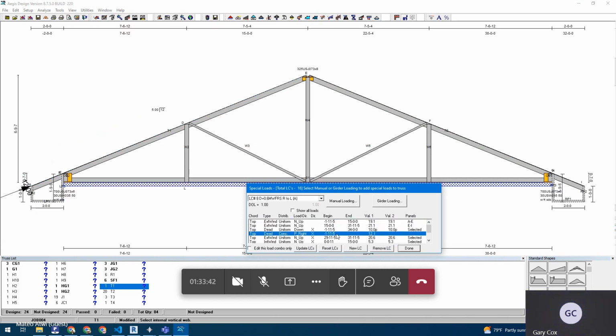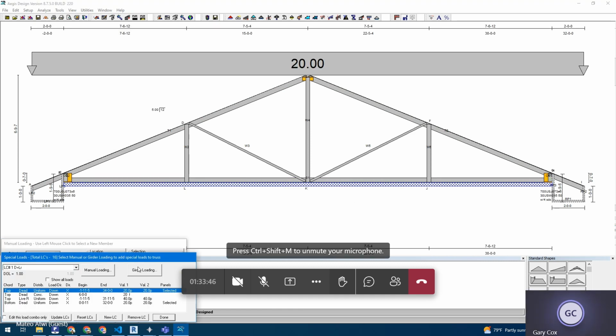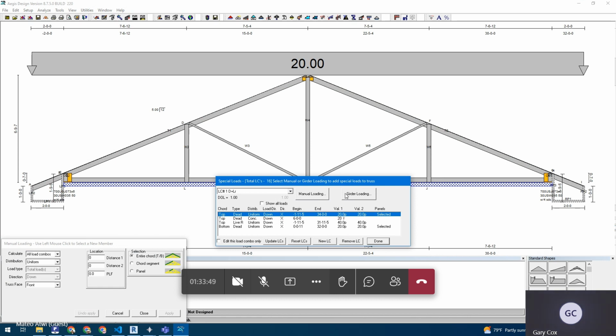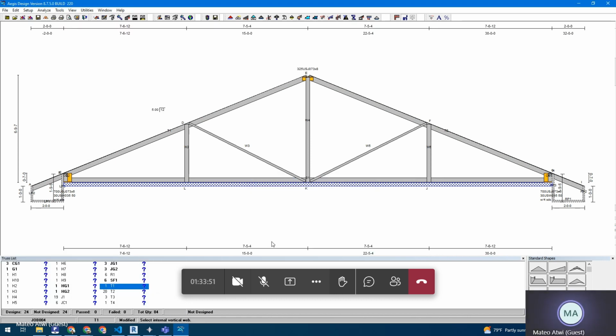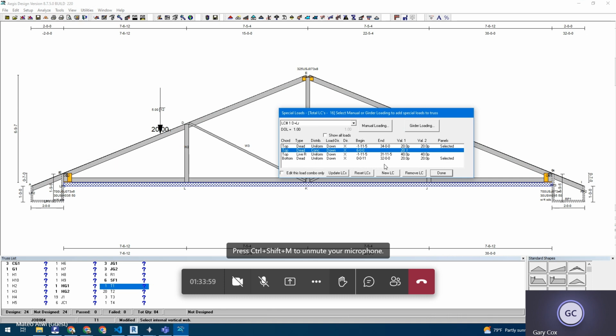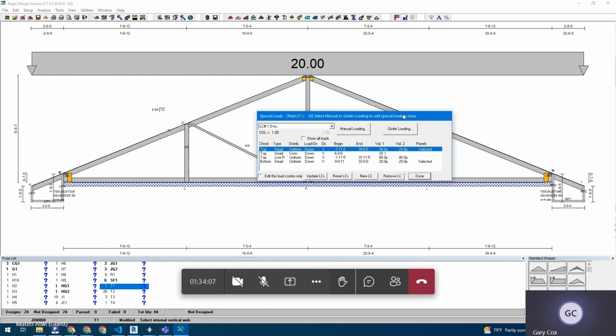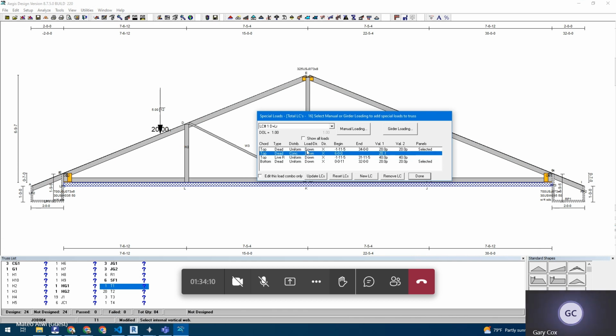A lot of it depends on how you added it too. No, I didn't put it. I might have to delete it, or oh, look, here it is. Update load. Make sure you don't click on update load cases. Yeah. If you told it to reset the load cases, all additional loads get removed.